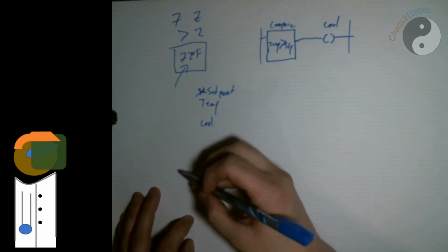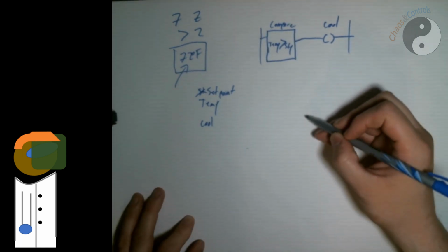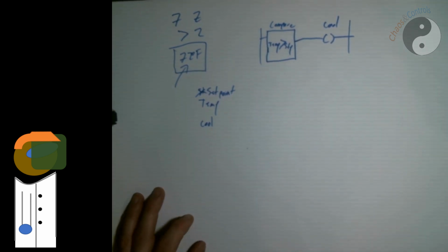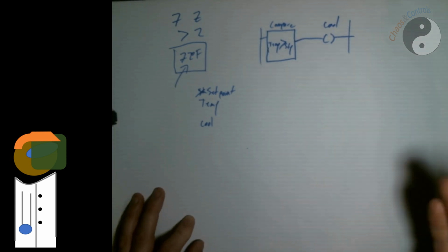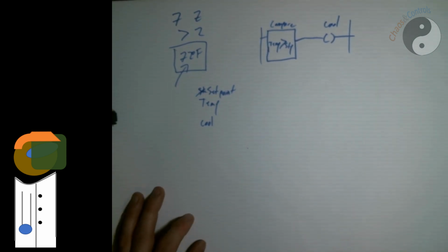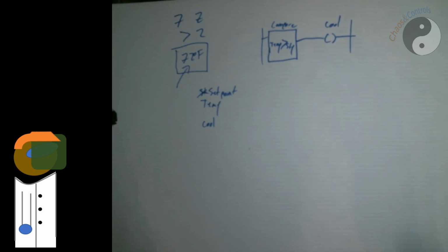And we're going to creep up and hit that and immediately turn on the compressor. And after just a very little amount of time, we're going to drop back below set point. And the compressor turns off. And then it heats up, and we turn on, and cools off, turn off, on, off, on, off, on, off. And as it turns out, compressors don't like to be turned on and off rapidly. Some things you can. Most things like to either be running or not running.